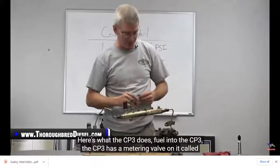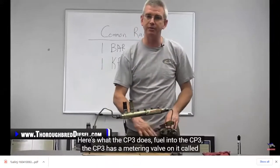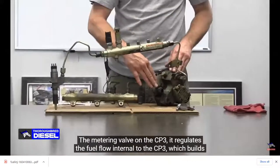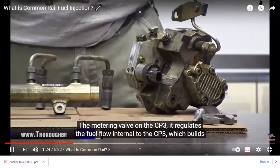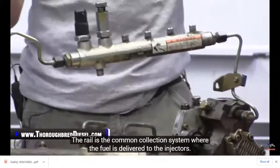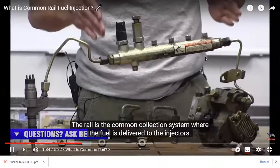Here's what the CP3 does. Fuel goes into the CP3. The CP3 has a metering valve on it called an FCA, or fuel control actuator. Some people call it an MPROP. The metering valve on the CP3 regulates the fuel flow internal to the CP3, which builds the pressure. That pressurized volume of fuel goes to the rail, the common rail. The rail is the common collection system where the fuel is delivered to the injectors.